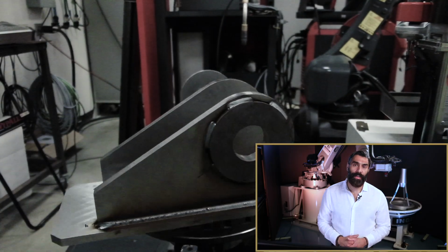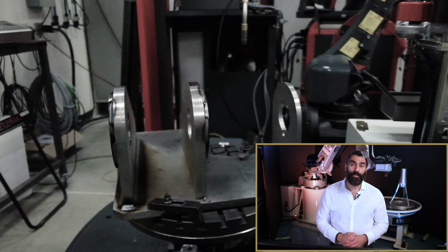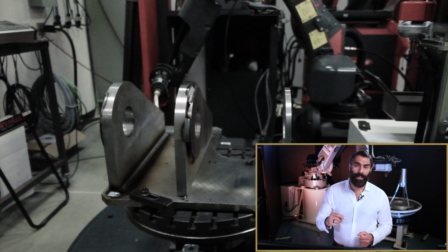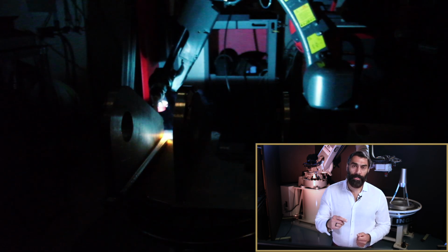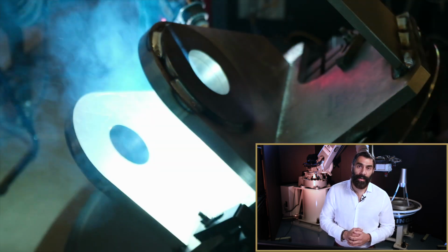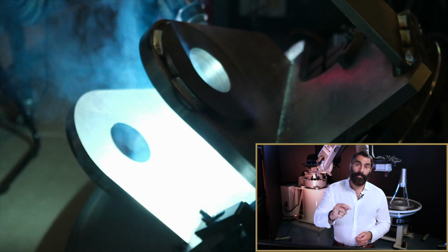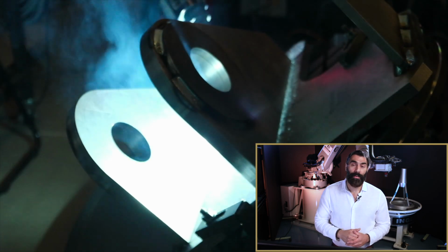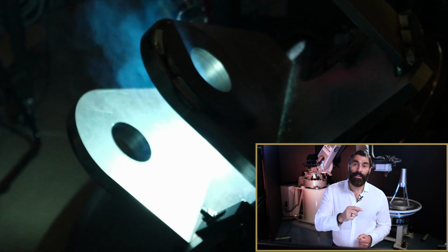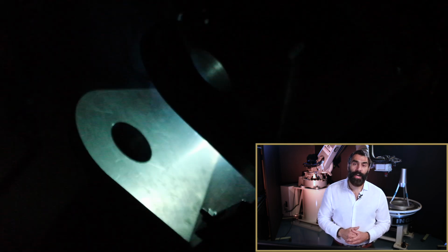The other technology is called seam tracking, and seam tracking allows the welding technology to understand if the seam is actually deviating from that straight line. So we have the start and end point, and if the seam is supposed to be straight, whereas in reality there's a slight curvature to it, the seam tracking technology can place the welding head exactly where it needs to go. Both of these technologies, the wire sense and seam tracking, are used throughout.